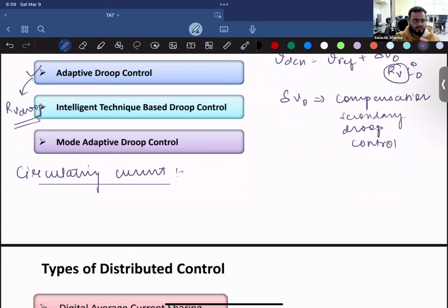In DC microgrids, which have DERs that have DC output, let's say solar panels, they are connected using DC to DC converters. These DC to DC converters regulate voltage and current flow. If your voltage is changed, your current will also change. And in a way, you can monitor and regulate the DC bus voltage using the DC to DC converter. Now let's say the lines connecting these DERs to the DC bus have different impedances.